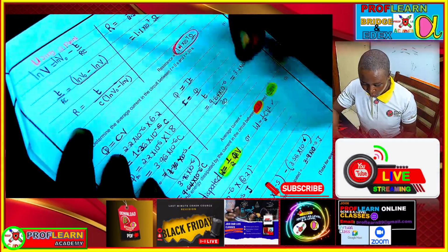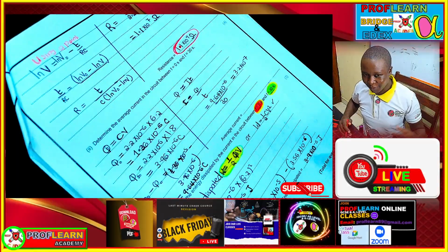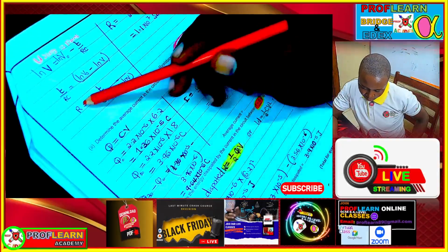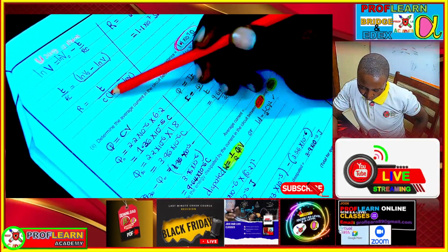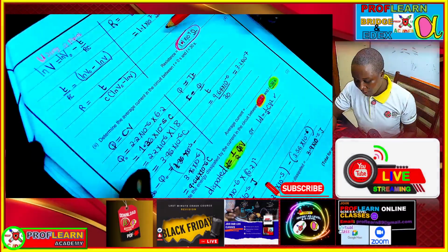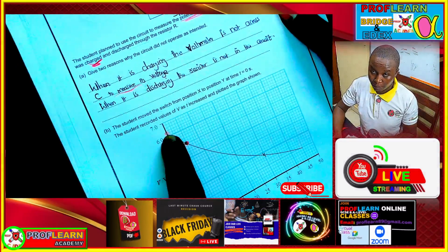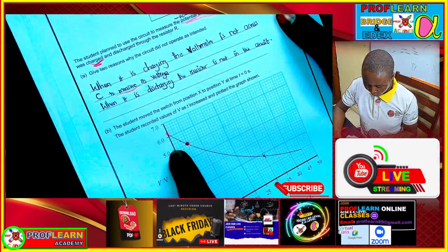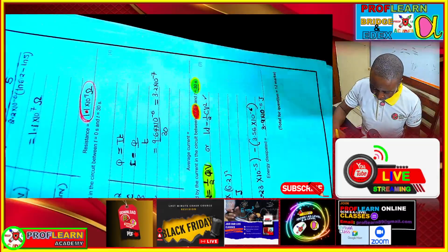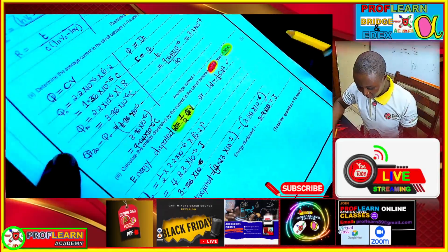So that we can make R the subject, we shall have R equals t over C times ln of V naught over V. Then if we substitute, because our V naught is this value that we have here, 6.2, V is 5, time is 5 seconds, and if you plug in, you'll get the value as 1.1 times 10 raised to the power 7 as the final answer in that case.